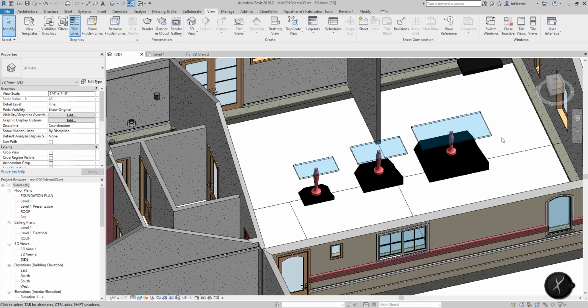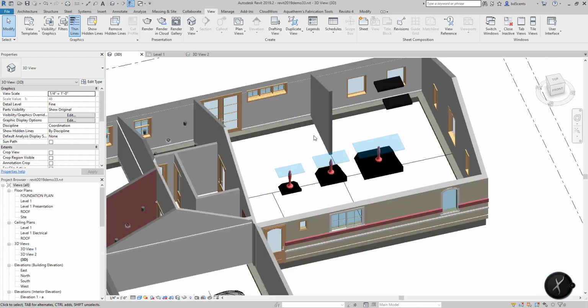Now, families and steps to creating families. The important parts are located on page 287 inside of the Gallatin College Revit book, and that may change. But currently it's to sketch it, do the math, make the associations through formulas, create the parameters, instance or type-based parameters, adding the formulas to add in what formulas exist, draw the reference material like we did, dimension the reference geometry, turn the dimensions into labels, which we did, and begin to flex that family. And then as we draw it, do the masses and line work associate. And then you'll align and lock the line work to the reference planes and reference lines and flex it. And that'll allow you to ensure that the families that you're creating function in a productive way.